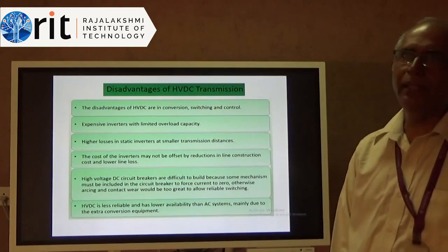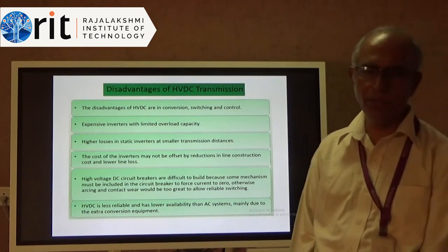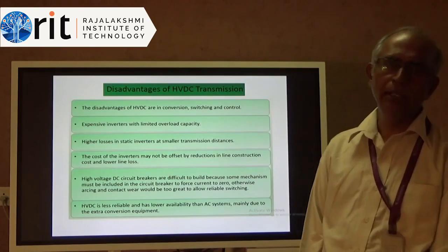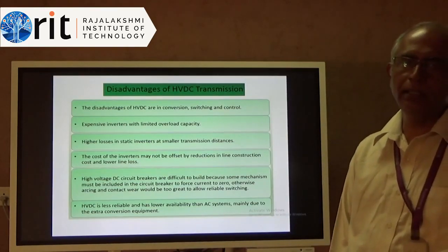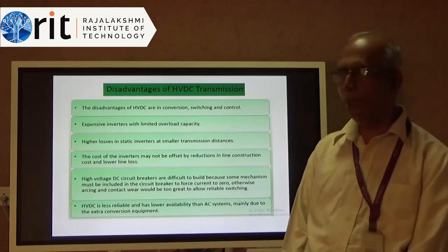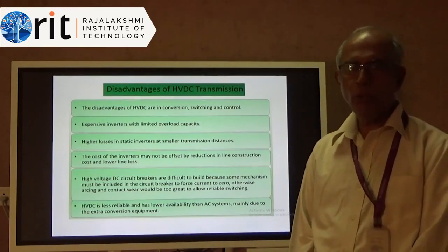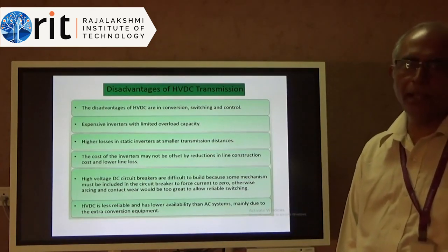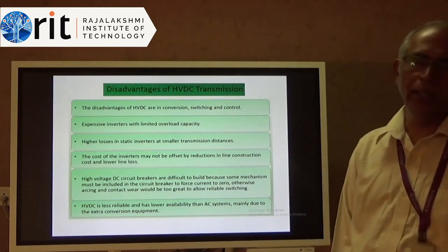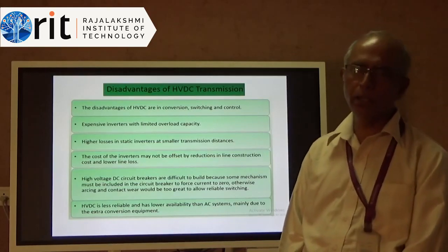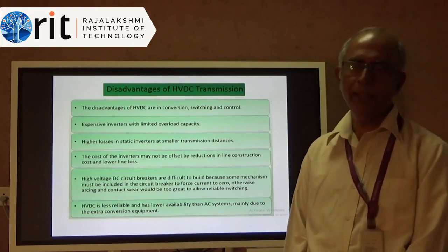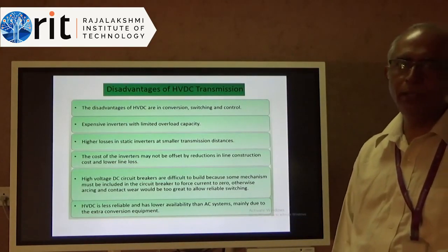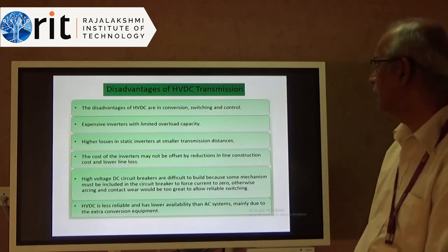So the amount of filtering or smoothing reactors that you are going to need is going to be much less when you use 12 pulse rectification. So invariably for all HVDC transmissions, people use a 12 pulse converter. More than 12 pulse also is feasible. Instead of 12 pulse, one could also go for a 24 pulse rectifier. But then imagine you need to have 2 more converters which are going to handle large power. So the economics does not work out. So people have calculated that by and large, a 12 pulse rectifier satisfies your ripple requirement as well as it is cost competitive, right?